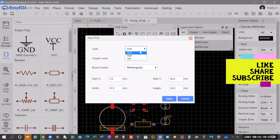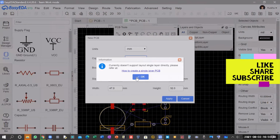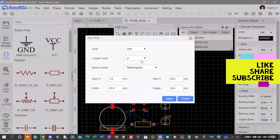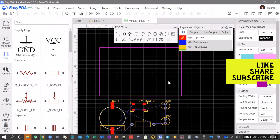And now units, we want mil, that's an easy unit. Copper layer, okay. So now PCBs have layers. So this is a single layered PCB, so do it one. Double layered PCB I will also be teaching you. Okay, so that's not a problem. You can even do it 8, but you will ultimately have the components placed on one layer itself. And the board will be custom. Let's do it custom. Yeah.